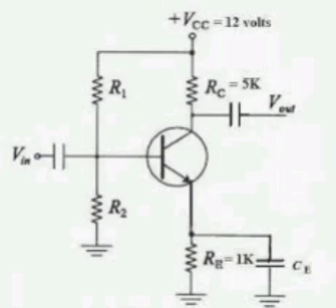For this, apply KCL at V1. At V1 you apply KCL, then you will get I1 plus 2V2 equal to V1 plus (2V1 minus V2) whole by 1 plus V1 by 1. I1 equal to 4V1 minus 3V2.